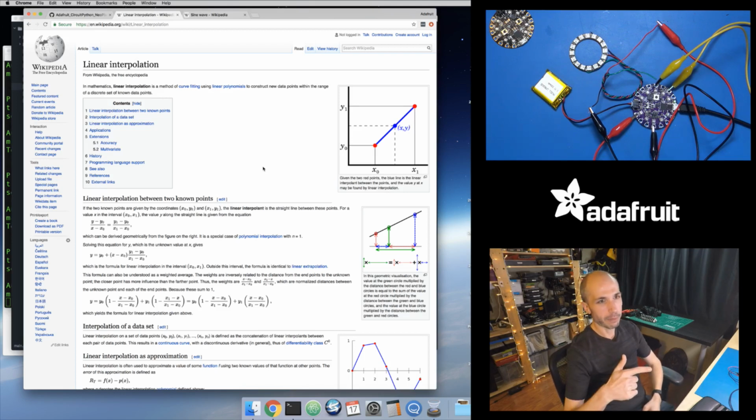I plug in the output of my sine wave, which goes from 1 to -1, and then I linearly interpolate so that, if the value I get from my sine function is 0, which is exactly halfway between -1 and 1, and I want to interpolate that into the range of 0 to 255, that would give me a value of 128, right in the middle of that 0 to 255 range. Likewise, if I get a value of -1 from my sine function, it'll give me one of the extremes, like 0, from my range of 0 to 255.